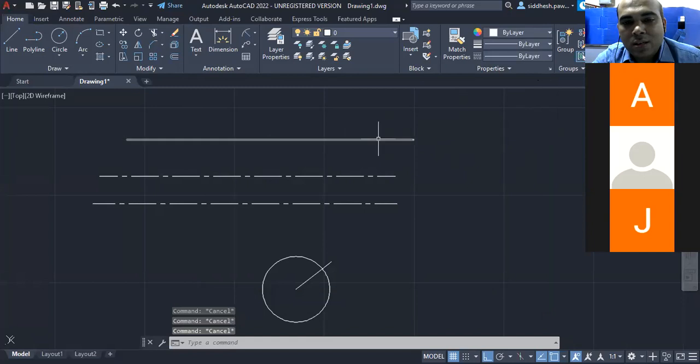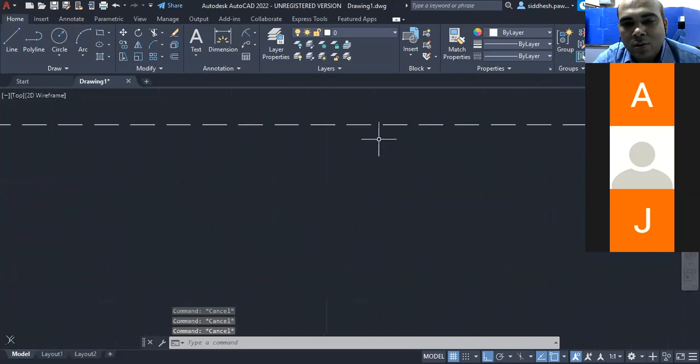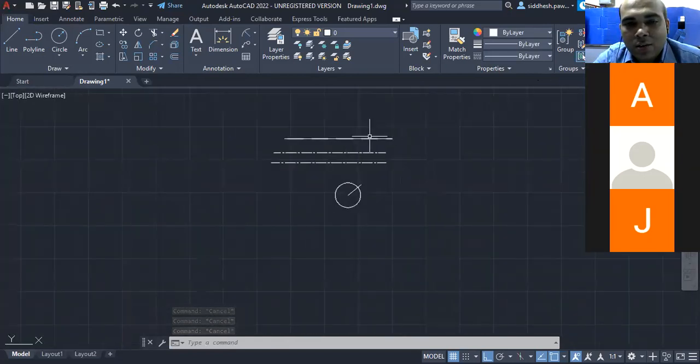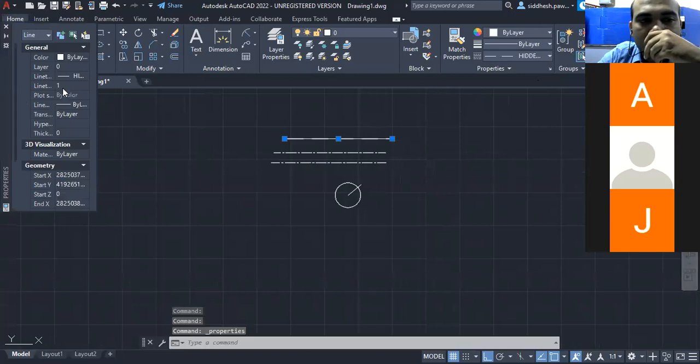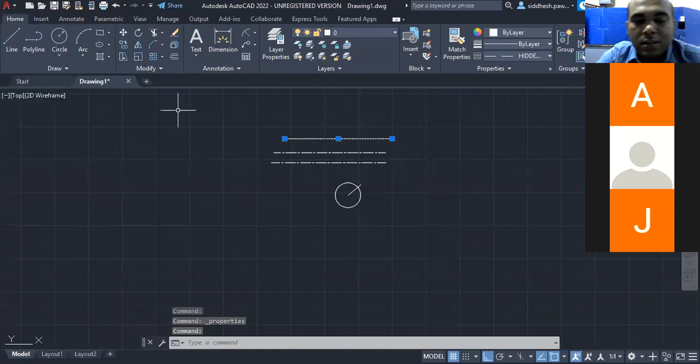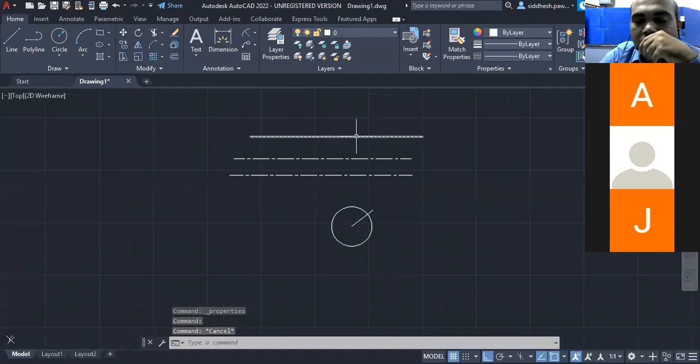This does not seem to be a hidden line, but when you zoom in, you'll get the hidden line. So what I'll do is I'll just select this. I'll go to property का ये arrow. This arrow I'll go with, and here I'll make a change in the line type. So line type, let's say I'm taking 20. Enter. So what I'm getting here is, escape. I'm getting a line as in a hidden line, but still it is not up to that mark.